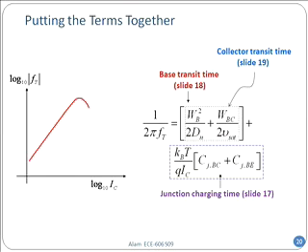However, what happens if you push too much collector current? At some point, it overwhelms the collector doping. Do you remember what that effect is called? Kirk effect, right? Where it overwhelms it. The base used to be WB, this tiny region. When so many electrons have flooded in, it has destroyed the junction, and as a result, the base has been pushed out all the way to the subcollector. Now I have this humongous base instead of the tiny one, right?